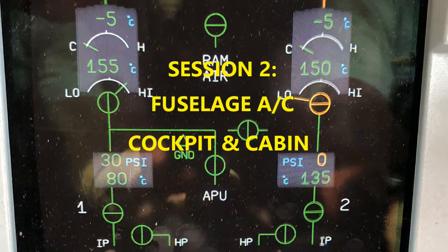You remember what I mentioned before: when you have a pack flow selector switch selected in the normal position, it's going to be 100% of normal airflow. If it's in the low position, LO, then that's actually 80% of the normal airflow. And if you do high, remember I mentioned this was a test question, by the way, in our session 1 overview, its high position is 120% of normal airflow. So that's what's happening when the push buttons are pushed, they're affecting the flow control valves.